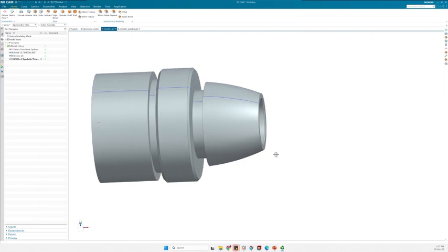In some cases, especially in the production of the same product, for these kinds of curves or form cutting, there might be some specific tools that the company manufactures, so that you don't need to go through the whole curve with a normal tool, but rather have a predefined form that will create this form, even if it is a simple or complex component, and you can manufacture it by a simple touch of the tool to your raw stock.